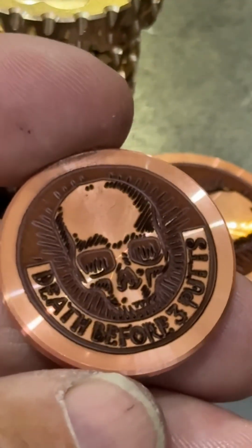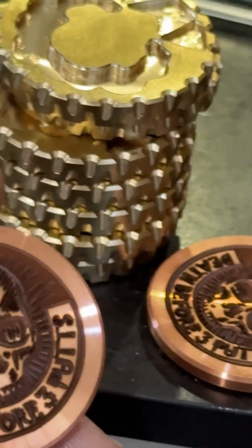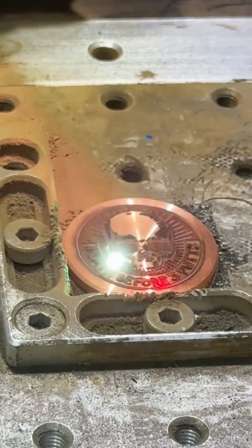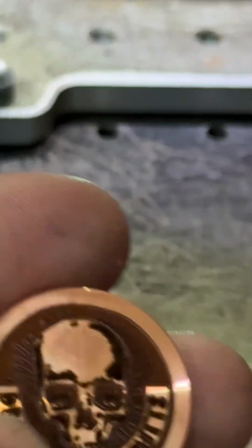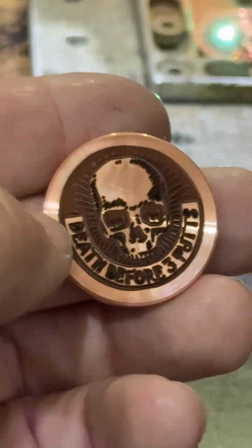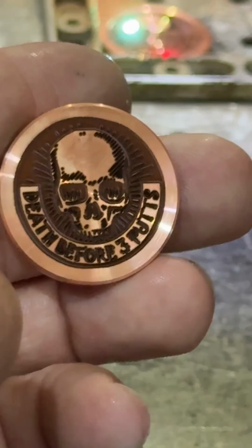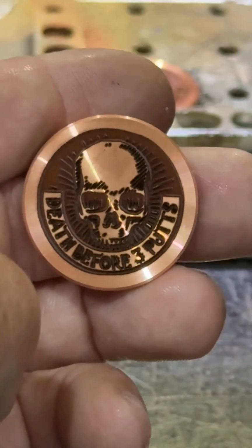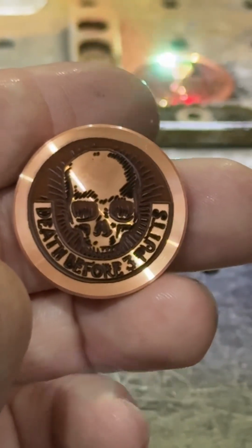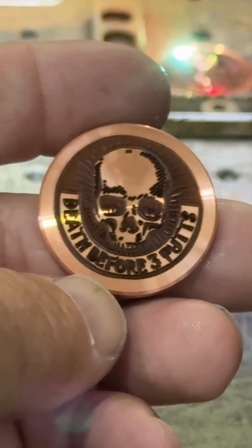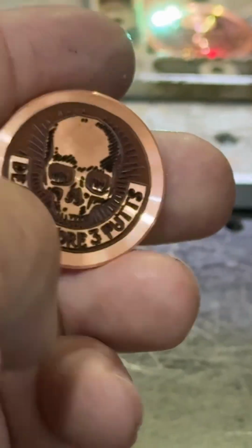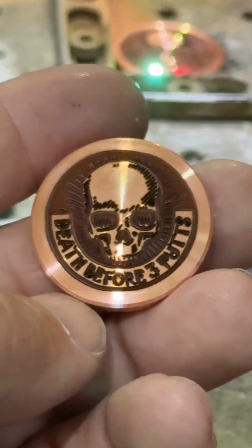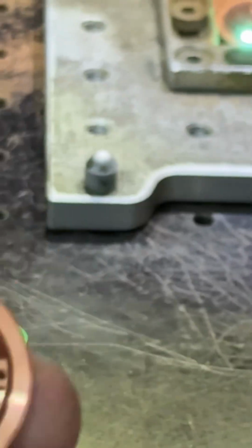But the other part to think about here as well is I've kind of dialed in this laser over time, where if I set it up against this rail, it's pretty much center. However, if you were to take some calipers and measure this edge against that edge side, it's off. Because that right there is placed by me eyeballing it as center. So again, the advantage to the mill, you have a probe that'll find the exact center of this piece and make it centered. Me, I'm eyeballing it on a laser, and that's all you can do there.